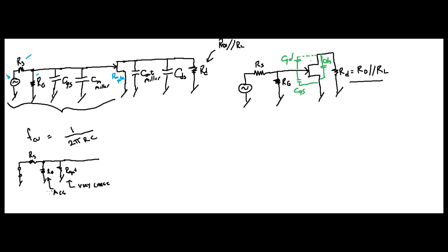Mega-ohms, high kilo-ohms. But your RS is going to be relatively low. Now look, if you have resistors in parallel, the current's going to tend to go through the least resistance, right? By Kirchhoff's law, the current coming into a node is going to distribute to these resistors, but all the current has to go somewhere, to ground, right? In this case, we're going to estimate that since these resistances are so high, it's all going to go through RS.